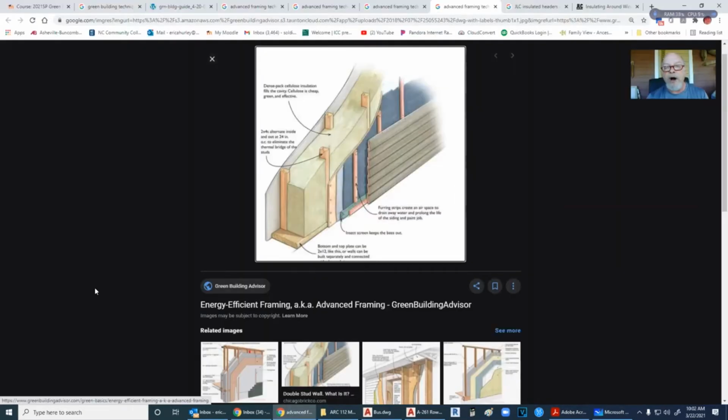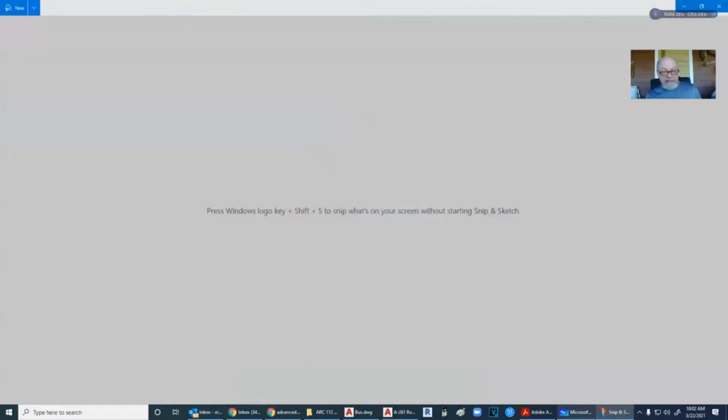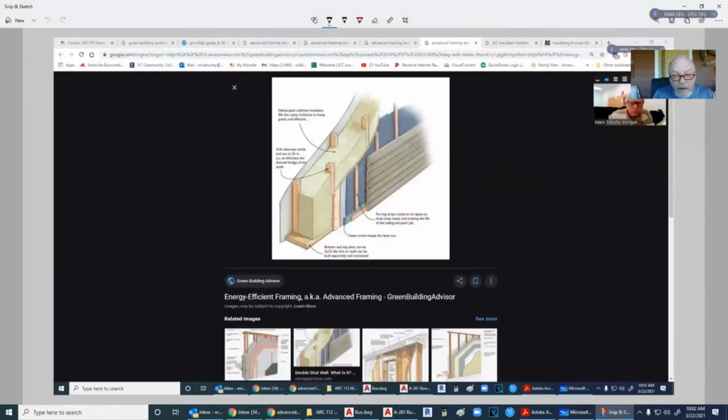Alternating non-conductive framing, and it is a freaking nightmare. These are actually put in at 24 inches, but they're offset, so you've got an inside and outside. These are 2x4s rather than 2x6s. What this boils down to is there's no way for heat to transfer through the wall.